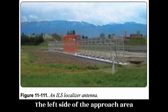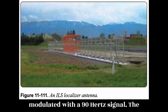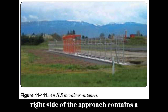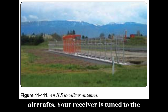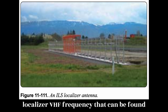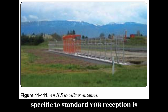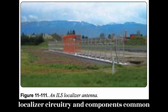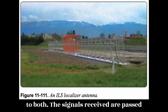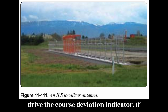The left side of the approach area is filled with a VHF carrier wave modulated with a 90 Hz signal. The right side of the approach contains a 150 Hz modulated signal. The aircraft's VOR receiver is tuned to the localizer VHF frequency that can be found on published approach plates and aeronautical charts. The circuitry specific to standard VOR reception is inactive while the receiver uses localizer circuitry and components common to both. The signals received are passed through filters and rectified into DC to drive the course deviation indicator.